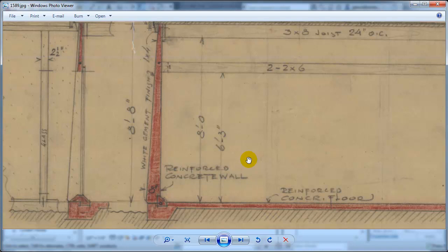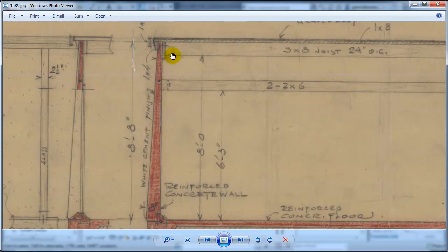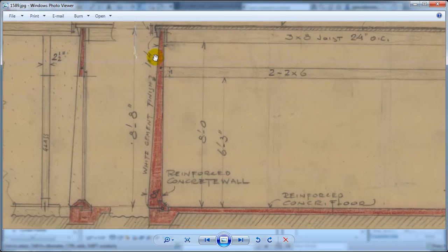I think Mary Lou was saying that they were actually poured in place and tilted up, right there on site. But just to sort of understand, it's kind of an unusual wall, and it's got a sloping surface. It's 8 inches deep at the bottom. I'm not sure how many inches it is at the top, probably only 2 or 3 inches at the top. It's got a flat surface and a sloping surface. It's got that little keyway down at the bottom, that little kicker to hold it in place in that foundation we looked at the other week.